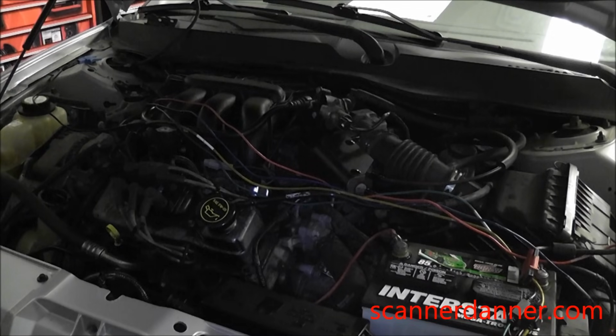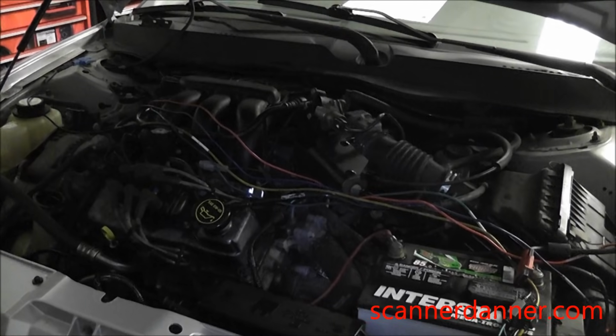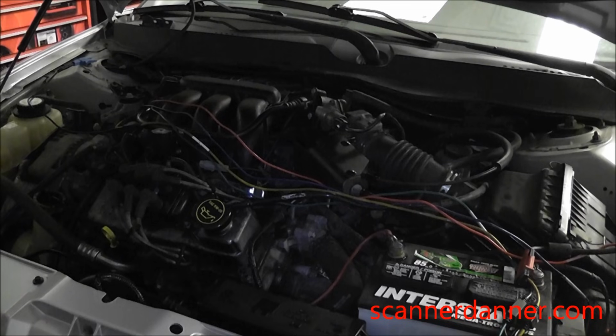Final thought on this Ford, guys, I forgot to mention it, was the test that we did for this cat. This was not for a restriction. We don't want to mix up restricted exhaust cat testing with efficiency cat testing. When you have an efficiency code for a cat, that does not mean you have a plugged up exhaust. You can also have a plugged up exhaust, which would be a melted cat, and not have an efficiency code. Two completely separate tests. You do back pressure testing for plugged exhausts. The efficiency test that we just showed you is not for low power conditions and things like that.